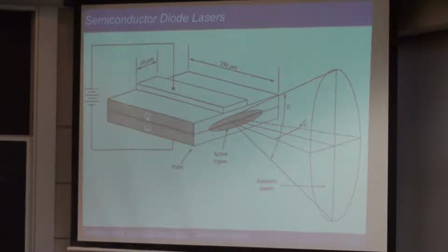But on the other hand, the advantages here really outweigh in some sense the disadvantages, because it's obviously very efficient. You can modulate it directly. You can turn it on and off directly. You can modulate the signal directly by just applying an AC voltage. So remember, if you're applying kilovolts, you cannot modulate it at a gigahertz frequency. It's very hard. If you have very high voltage, you cannot modulate it fast enough. But here it's very easy. In fact, not just easy, it is actually regularly used for optical communications and such, right?